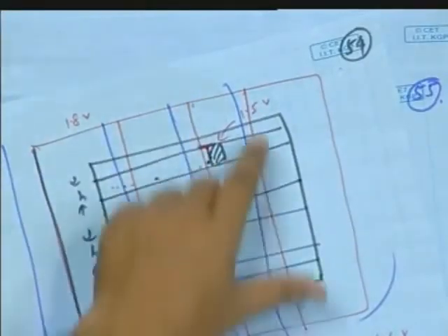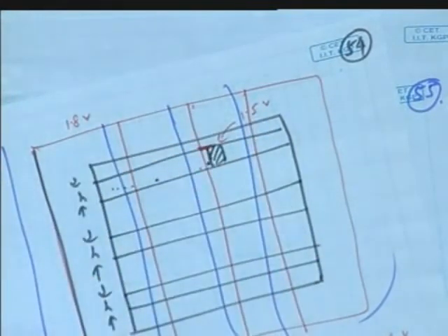No, that's what it is, right? These things are generally done in one single layer. So this is done in metal 1, and these things are done in say metal 3. Means the whole layer is totally ground or the whole layer is power. It depends. His question is whether I will have a dedicated layer, say metal 1, the first layer, for ground, with all the wires going to ground. But that's a poor utilization.